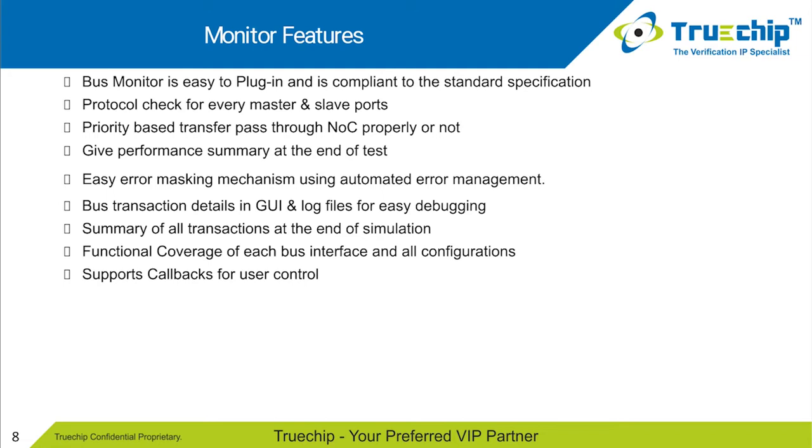Apart from that, burst transaction detail in the GUI and log file is also provided for easy debugging, along with a summary of all the transactions at the end of simulation: how many incrementing transfers there are, how many wrapping transfers, how many fixed transfers, and in the TileLink case, put and get transfers and arithmetic transfers.